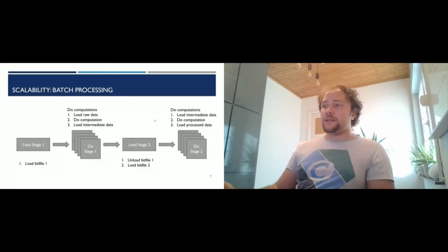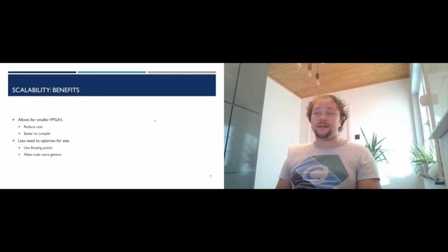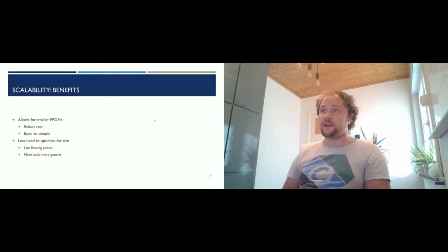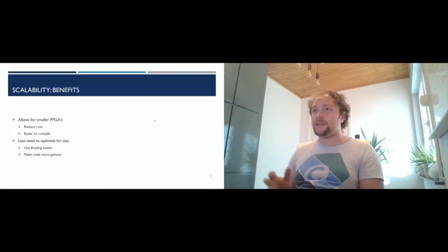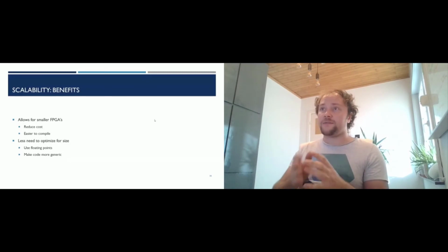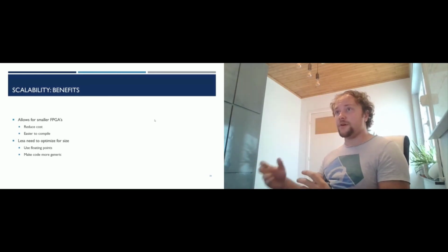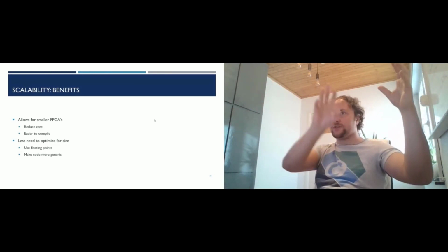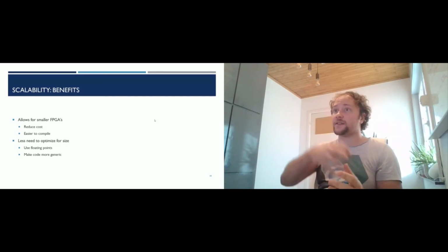Now, the benefit of this strategy is actually twofold. It's both cost-effective, and it also saves you some time if you implement it. It allows for smaller FPGAs. So let's say your customer doesn't have the money or is working on a really big scale, then it's quite easy to just go for a smaller FPGA, and if for some reason you need more processing, just load in bit files as you go. Also, it's easier to compile, so you're only altering one bit file. Instead of having one big thing that you need to recompile, you're just changing your one small bit file, like recompiling a certain VI instead of your entire project.